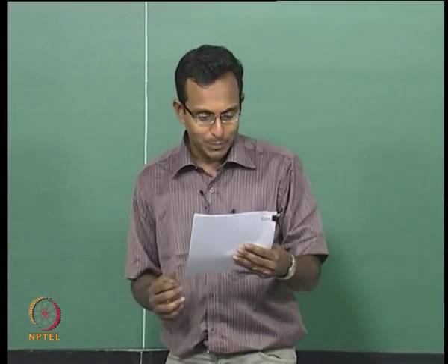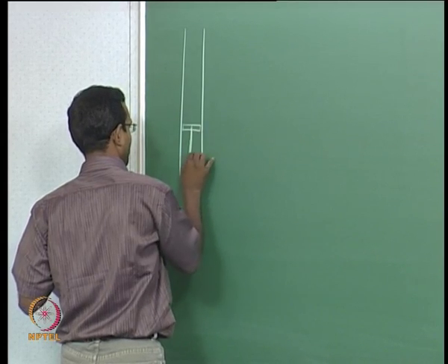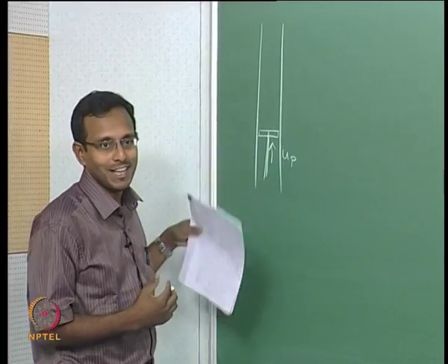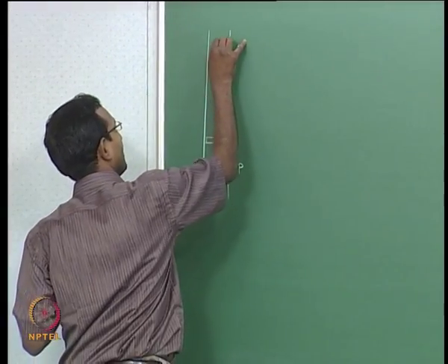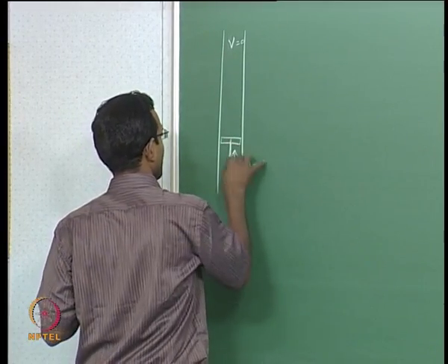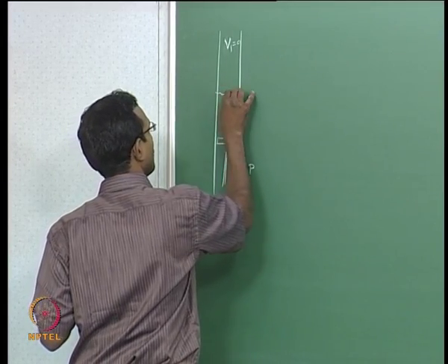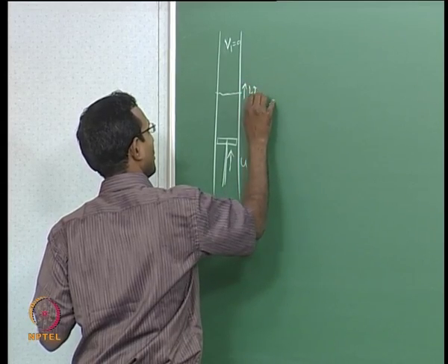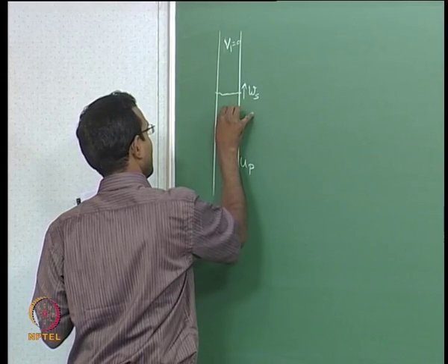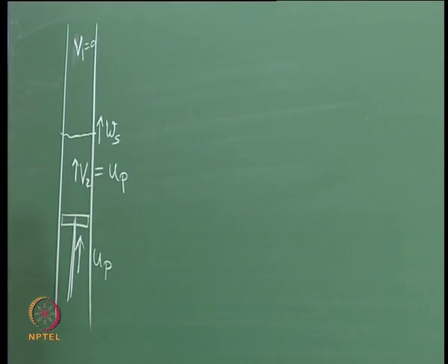So what we do is we will just go and pick up expressions that we already derived. So you will remember the moving shock problem, where a piston is going this way, velocity up. We did not solve the problem like this. In a way, we solved it as a numerical example in one situation like this. Okay. Initially I said that u equal to 0, actually we used v variable with respect to the lab coordinates. Okay. With respect to shock coordinates, it was u variable. That is what we used. Okay. This is going to be v, and v1 was 0, and the v2, if there is a shock and the shock is moving with velocity ws, we used. If it is traveling with ws, then the velocity behind with respect to outside lab coordinates, v2 is equal to my up, the piston velocity. That is the job of this particular shock wave. That is the overall idea.